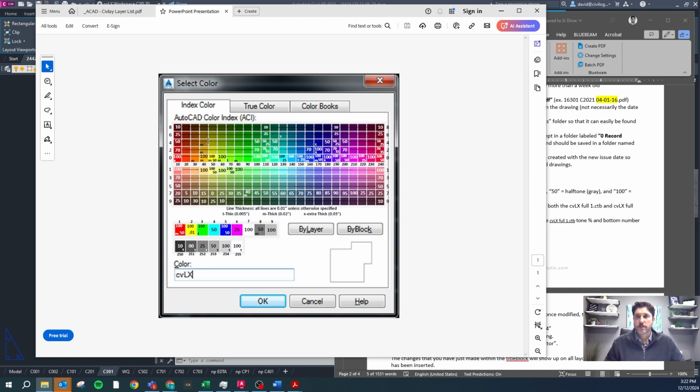We can make lines thick or thin, we can make them solid or dashed or different types of dashes, and we can make them white, different shades of gray, or black. So we have 3 different kinds of metrics to display information differently, and this shows you about the thickness and the color. So the number that's in there is a percentage of black. So 5 would be 5% black, which means it's 95% white. It's a really light gray.